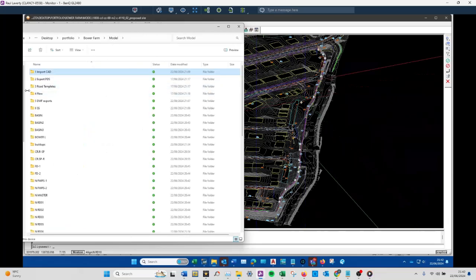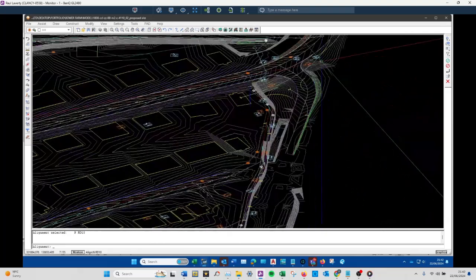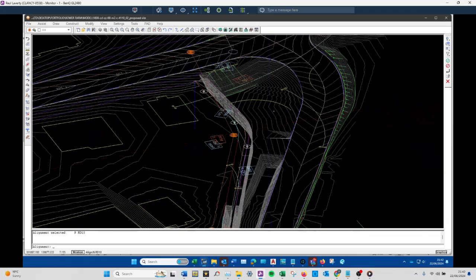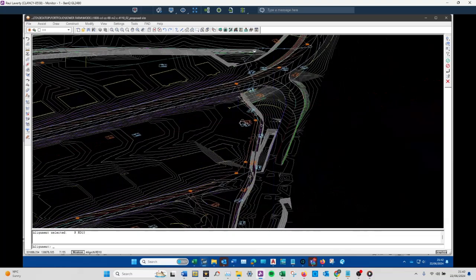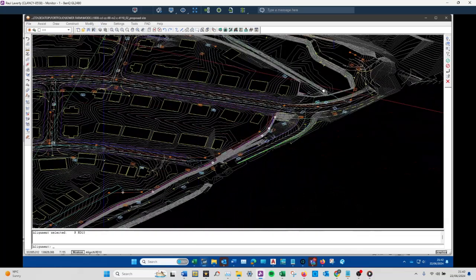And even if you say, well, I'll just use an XREF, even when using an XREF, sometimes you want to edit it by maybe putting in ROW center lines because they didn't put in ROW center lines, and you're going to do the ROW alignment. And you don't want to mess up those XREFs because it could end up messing up your drawings.